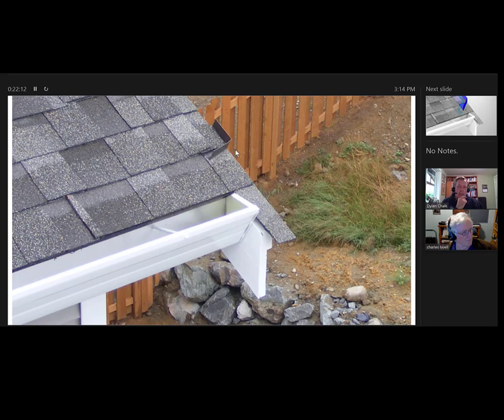and should arguably have redirect flashings. This is kind of the final thing we wanted to talk about today. But here's a great image of just trying to prevent all the water from rushing down here. I don't know about you, but you see this detail on a rainy day and you walk under there and you get soaking wet. Tremendous amounts of water can shed off that little 2 inch or 3 inch strip, depending on how big the roof is and how much the roof overhang sags. So redirect flashing is really important.